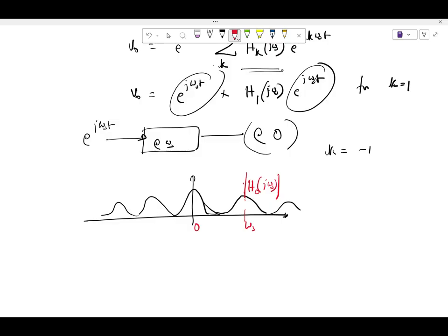the peak that I am getting is the 0th sideband, right? Which is a fundamental sideband, essentially, right? If I have to find out the -1th sideband, right, what should I look at? No, -1 means left side, right? So this I should get H -1, right? And so on, right? So at one shot, right? So all we did was find out the transfer function at T on. That's all we did. And that is not very difficult to do, right?